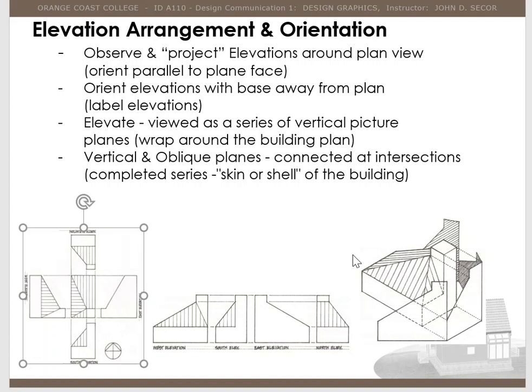So how we arrange this. When you observe your project, it all really revolves around your plan view, okay? So once that plan view is in the middle and you bring out those lines like we did in the past, this is the key. You want to make sure that you have a true north. So you identify each elevation as north and south, east and west.